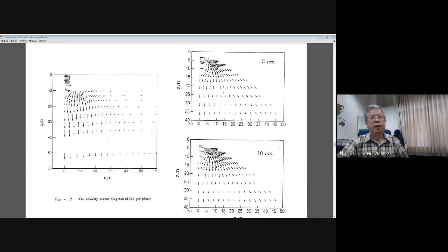Droplet velocity is high because they are just coming from the injector, and they have a strong axial momentum and are concentrated in a small region. This tells you the region of your spray, and that region will extend further downstream. And here you can easily see there is a recirculation zone, which tells you the droplet velocity vectors change their directions in these recirculation regions.